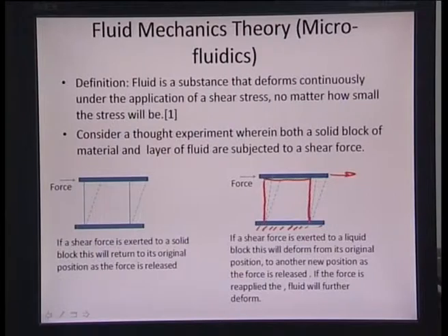And then you try to move this fluid as a plug along with this plate by moving the plate in the forward direction. As you can see here, the fluid would shear up without returning back. There is some molecular deformation where this fluid will tend to remain in a sheared condition. If you apply some more force, it will shear to a different condition here. Okay. So there is a continuous shear process happening because of movement of the upper plate with respect